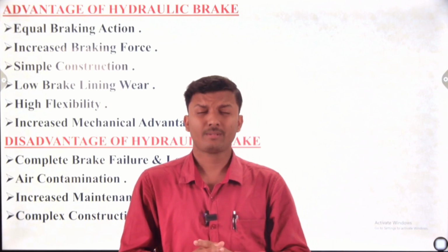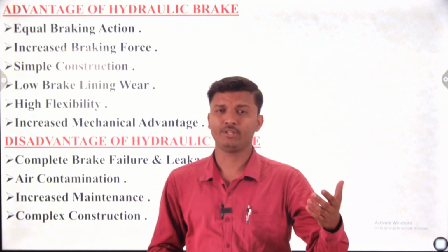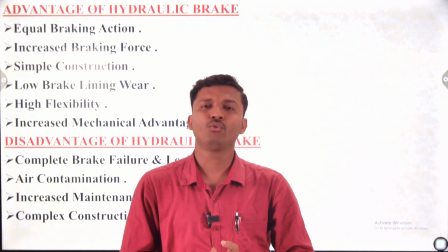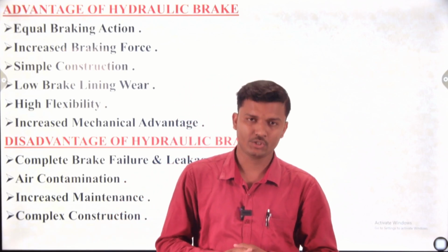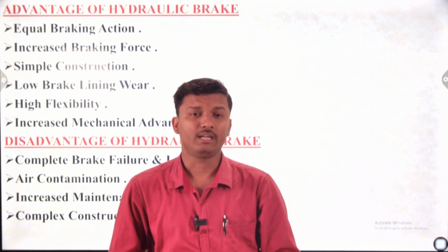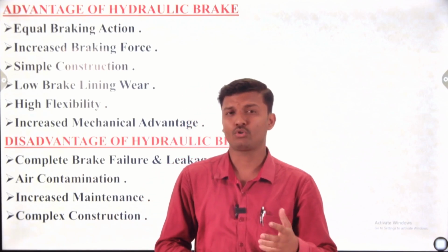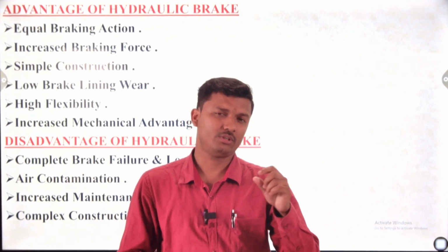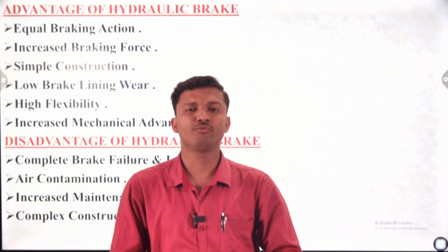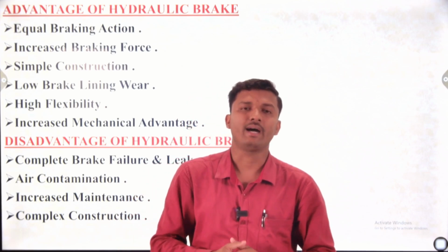Then increased braking force. Increased braking force means with very little effort we can increase the braking forces. Simple construction, not very complex. Then low brake lining wear. The wear and tear of this system is very less, and then high flexibility. The flexibility is also very high, and the maintenance cost is also not so high, but it certainly increases compared with the mechanical brake. Increased mechanical advantage means the efficiency of the braking system is much higher than the mechanical drum brake.